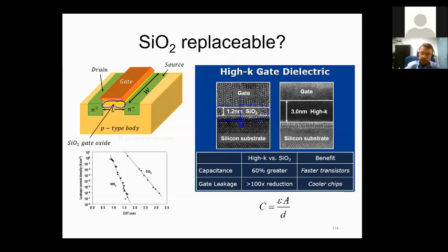You change that with what we call high K dielectrics to put a little barrier for the electrons, and these high K dielectrics will withstand these electric fields and will stop the electron conduction from the gate down to the silicon. If you stop that, you will also prevent the leakage of the current too. The current won't be leaked away, so you consume less and less power. Hafnium oxide is one of those types of oxides, unlike the silicon dioxide, so it doesn't allow the leakage current to occur.